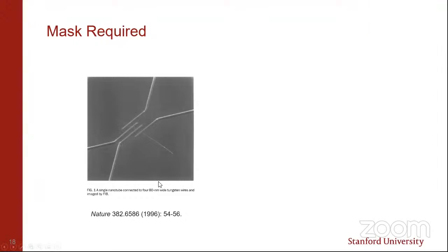Okay. So the feature size is one thing. In this image, for example, it's 80 nanometers, which is the width of the wire. I'm guessing the sharpness of the edge is probably like 10 nanometers or something like that. Okay, cool, thanks. The reason why we use gallium as the ion source is that, as one of the major reasons, the gallium beam can be confined to a probe size of less than 10 nanometers. I see, okay. So if less than 10 nanometers, you'll be able to fabricate features of at least 50 or 100 nanometers.